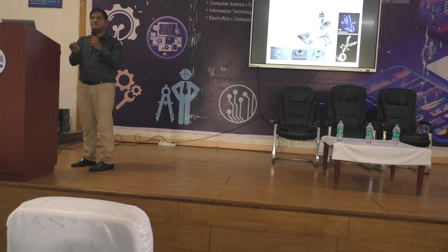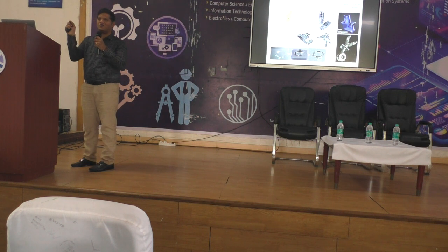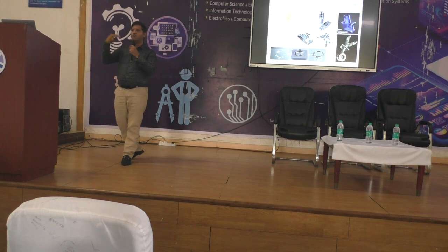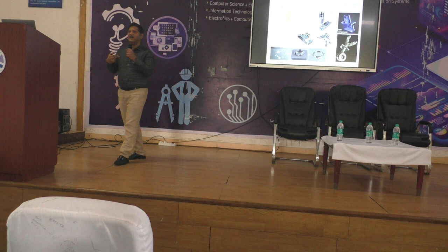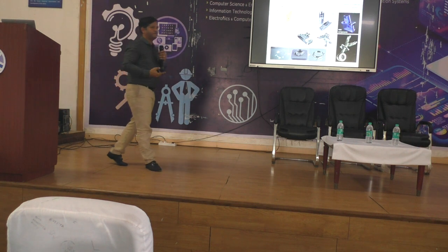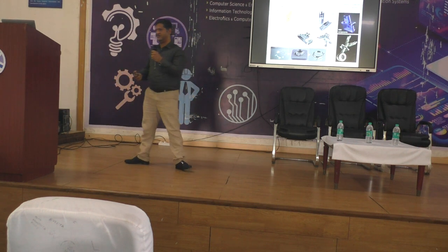If you want to go with conventional manufacturing, you need to manufacture the separate components and assemble them to make this injector. Here you can reduce the number of components from 19 to 1 with the help of additive manufacturing. Such kinds of components fall under region 3. At that time, additive manufacturing is preferable over the conventional manufacturing process.